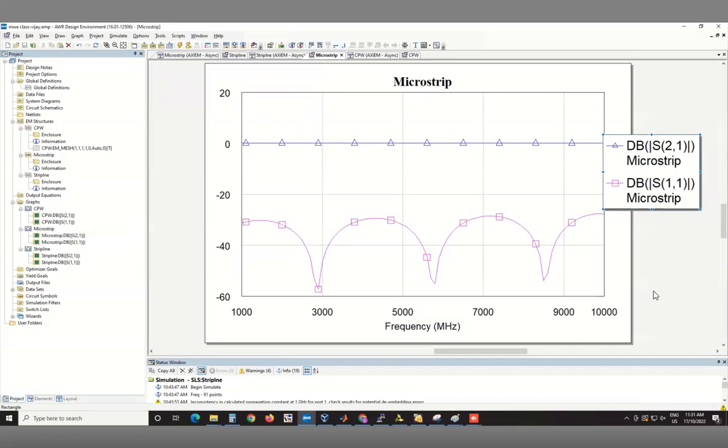This is a perfectly fine 50 ohm transmission line. And you will see these kinds of responses even when you measure real transmission lines in your lab using, say, a vector network analyzer. What is happening at these points is some interference condition is giving you zero reflection.